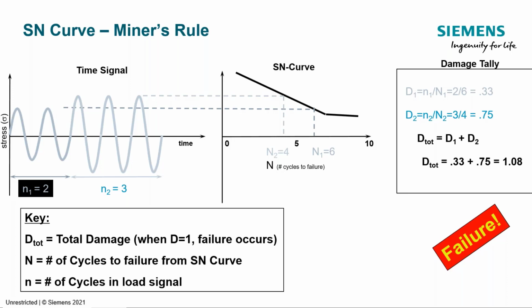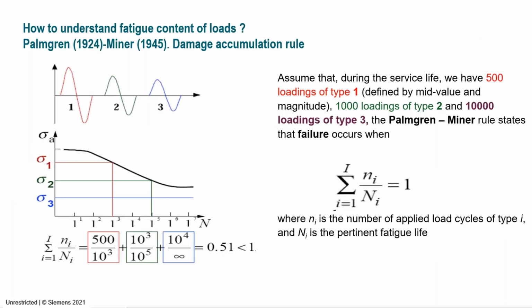If you're doing a test and you're doing one of these rigs and you're exciting it, generally ballpark rule of thumb's 10 degrees. You don't want to raise anything more than 10 degrees. So it's rate independent. We just count cycles. It's easy to count cycles on a sine wave. If you like a more mathematical formulation, here's one.